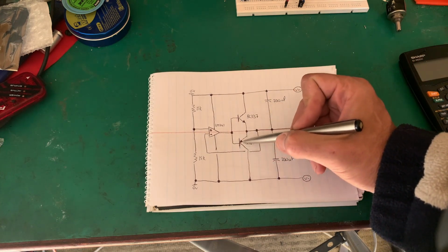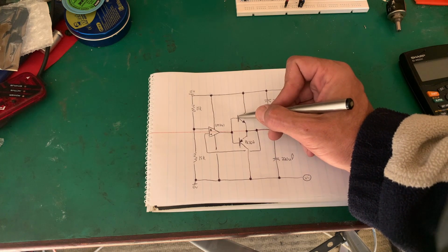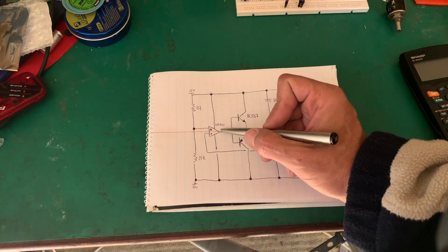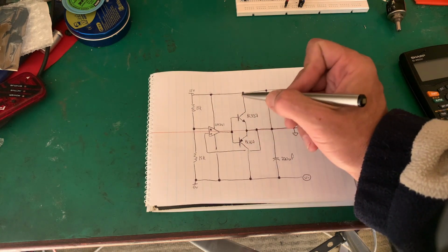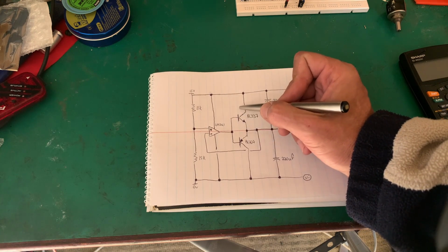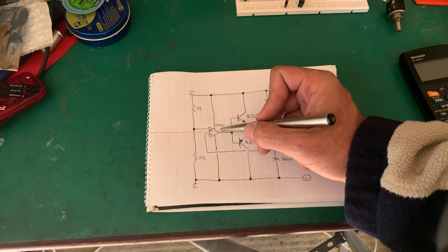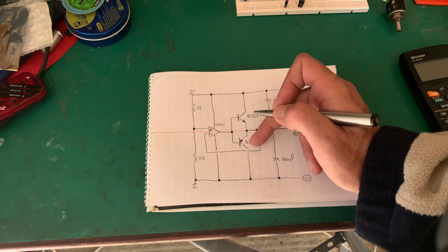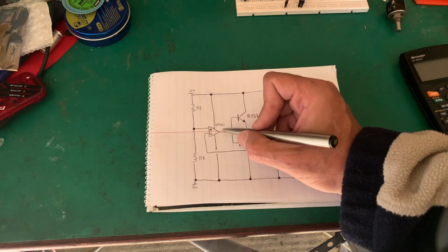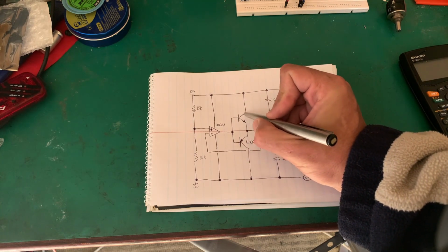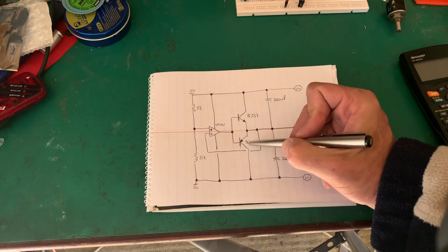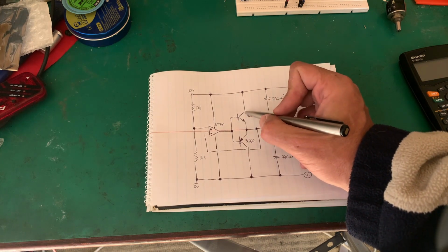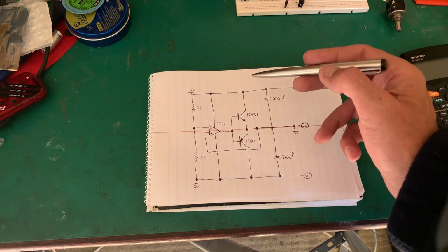And we come to this push-pull arrangement here. You'll see I've got an NPN transistor, a PNP transistor. Let's think of this for a moment. If that output goes up, it's going to switch that transistor more on. If that output goes low, it's going to switch that transistor more off. Now conversely with a PNP, remember it works the opposite. If the output's going up, I'm switching this one off more. The output goes down, I'm switching this one on more. Not too difficult.